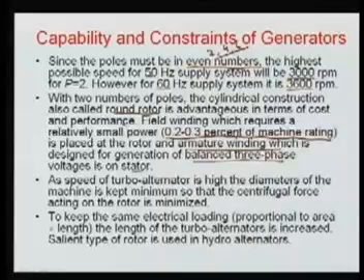Means the rotor where we put the field. Now you can assume that you have seen the DC machines. Normally the field is on the stator and on the rotor we have the rotor winding. But here it is different: your field winding is on your rotor, where the armature winding is on your stator.